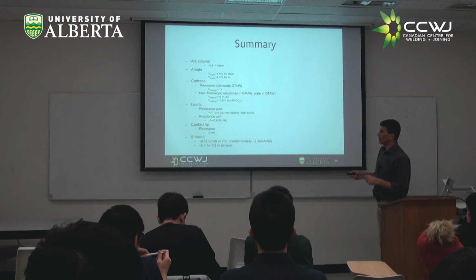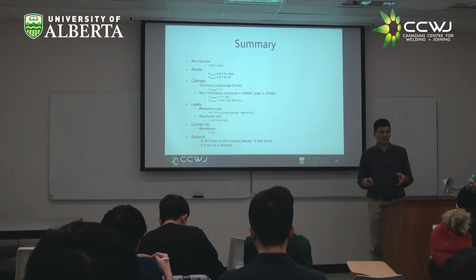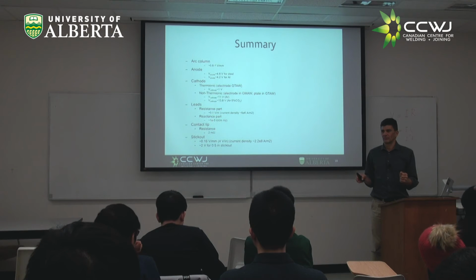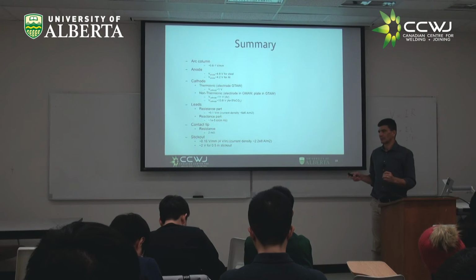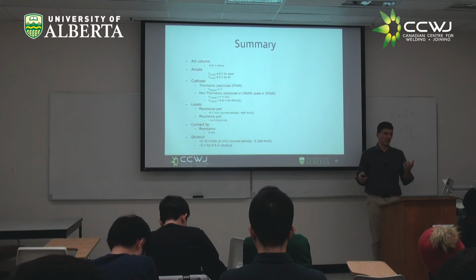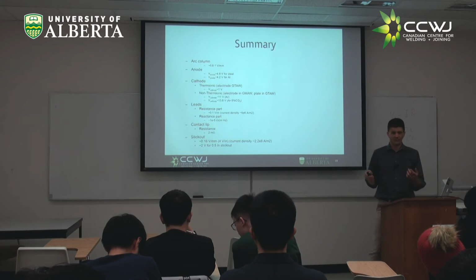At the contact tip, we're going to call the resistance 2 milliohms, right? And at 200 amps, with the 2 milliohms, how much power is that? It's 0.4 volts times the 200 amps. That would be 80 watts, right?